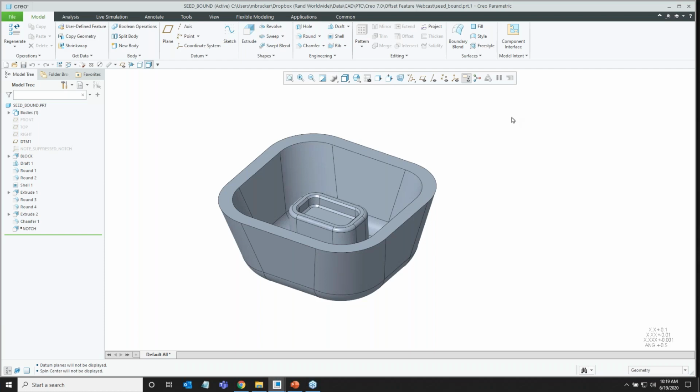In this process, Creo is going to pick the seed surface that you select, but it's also going to select all the surfaces that touch the seed and all the surfaces that touch that bigger set, up to, and not including, a boundary surface that you pick while holding the Shift key. So for the inside of this model, there's about 200 surfaces here. I want to pick all of them.